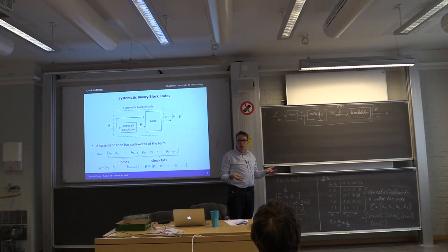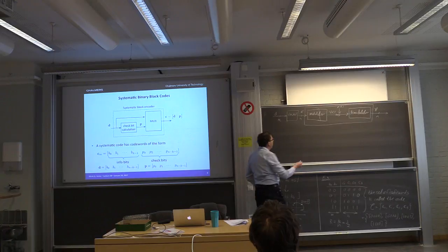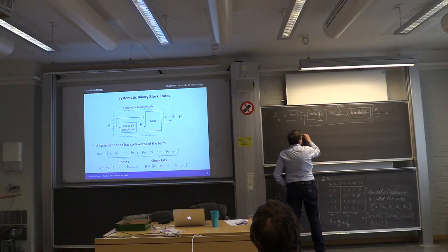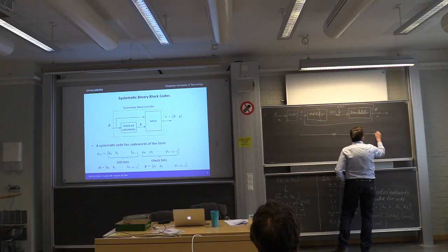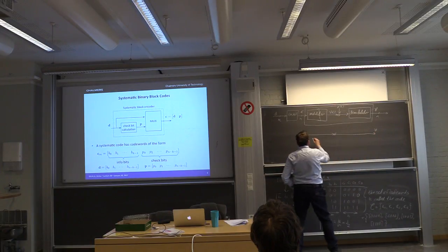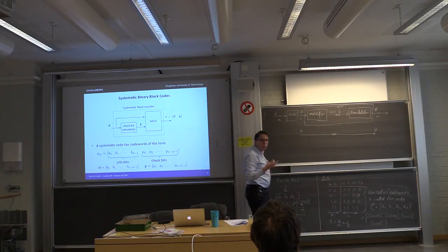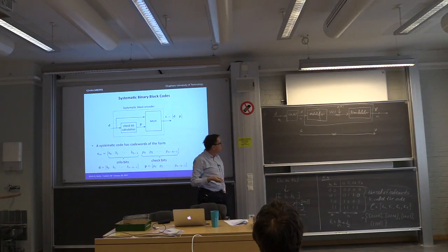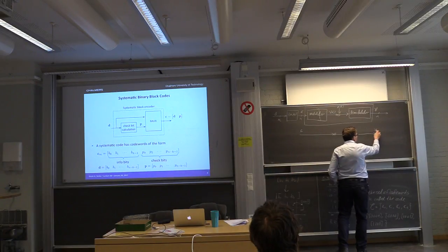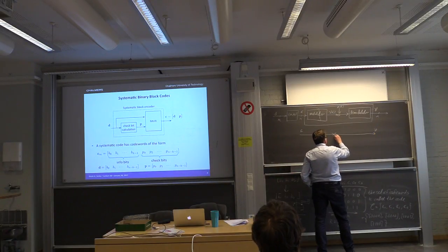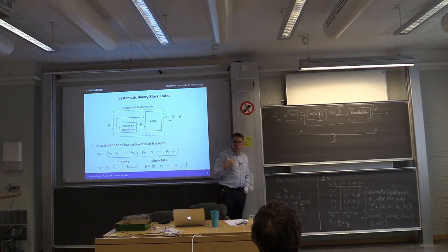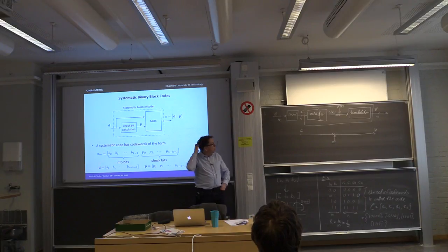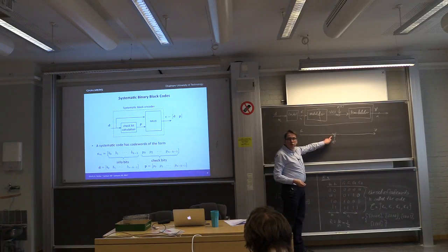The block diagram for that is quite simple. It should have the same input-output as before. So the input should be the code word, whatever code word we chose to transmit. Then something happens on the channel, and we get output bits here. What happens on the channel is that we add on an error pattern, where this addition is modulo 2.